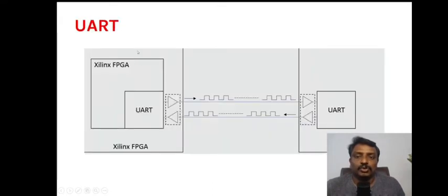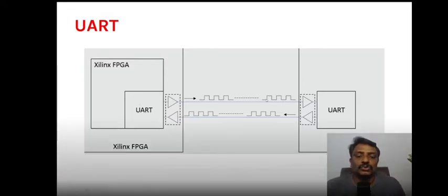So coming to UART, if you check this block diagram, you have this transmitter. This is an FPGA or a microcontroller, where the microcontroller's transmitting port has to be connected to the receiving port of the PC. The receiver of the PC or host is connected to the microcontroller; the transmitter is connected to the microcontroller's receiver port. Okay, so